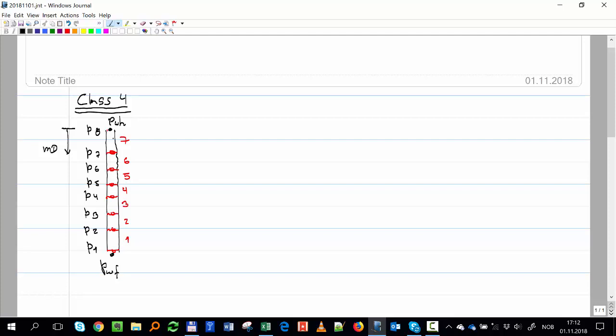But if you see, in essence, it's the same problem. The only thing is that the pipe segment is shorter. The space in the tubing that we're looking at is now this piece of pipe. If we now try to split, we will have segment 1, which will be PWF, and here you'll have P2 out, with a rate of gas coming.